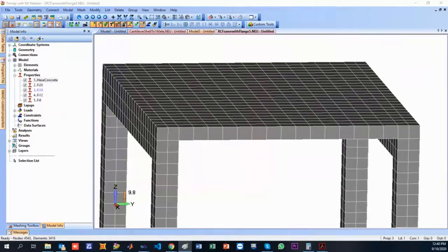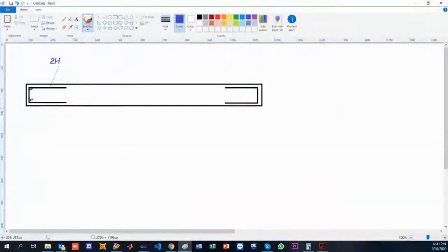Okay, so if I have, let's say, a section of my slab, then I have to apply a U-shaped reinforcement here. So this is from this side, of course, and 8 millimeters every 15 centimeters will do. And of course, the length here should be at least 2h, where h is the thickness of your slab. And don't forget that you will also place a rebar there along the direction here, this one. So if this is your slab, you have a U-shaped here and a U-shaped there.